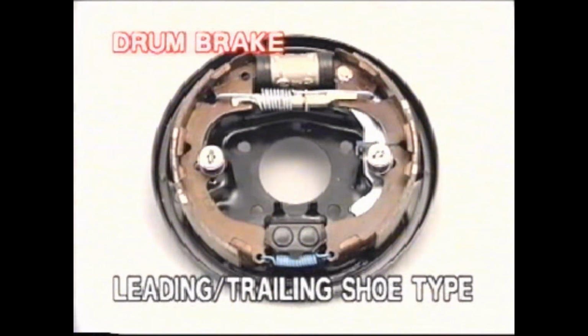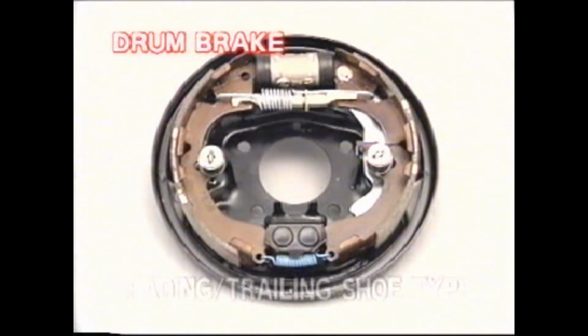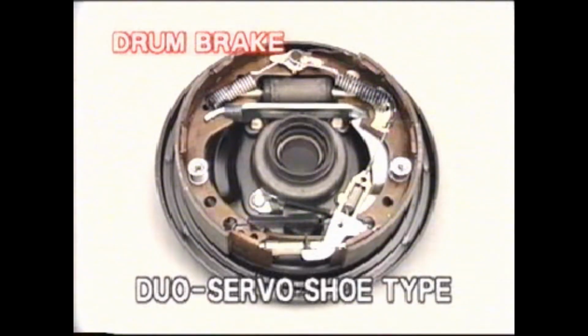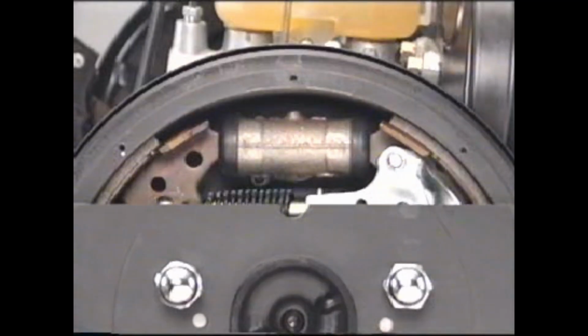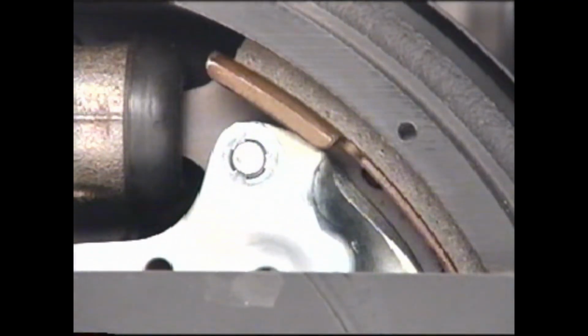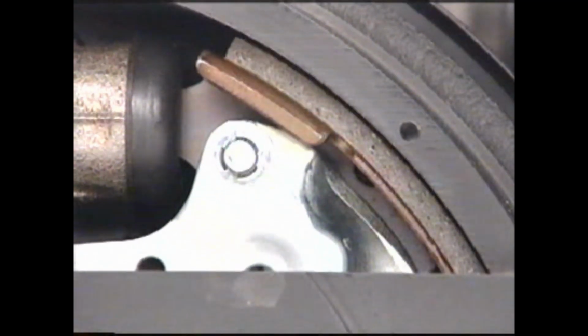Types of drum brakes depend on shoe installation or number of cylinders. For example, the leading trailing shoe type, 2 leading shoe type, and duo servo shoe type. The hydraulic pressure transmitted to the wheel cylinder forces the shoes apart. The lining installed outside the shoe rubs against the drum revolving with the wheel and produces brake force.